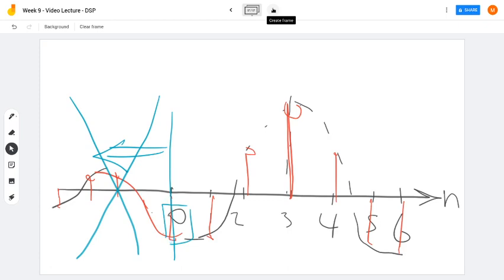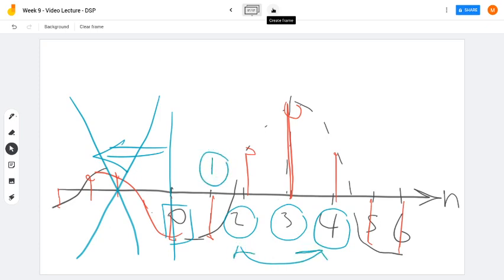And the symmetry is very important in the impulse response. So that's why we will keep samples up until we have the symmetry achieved. In other words, if we take the sample at 3, we will take a sample at 2 and at 4 because they are symmetric to each other. And the sample at 1, let's say, is symmetric with the sample at 5. So I will keep this sample and the one at 5. And the sample at 0 is symmetric with the sample at 6.